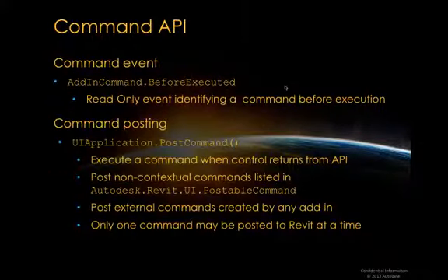Another very exciting area is the new command API. Previously, there was no way whatsoever for an add-in to launch a built-in Revit command. This has now changed. You have the possibility to post a command. There are obviously a number of restrictions of when this can happen and what kind of commands can be launched. But the good news is it is possible, and there's a list of the postable commands in an enumeration.